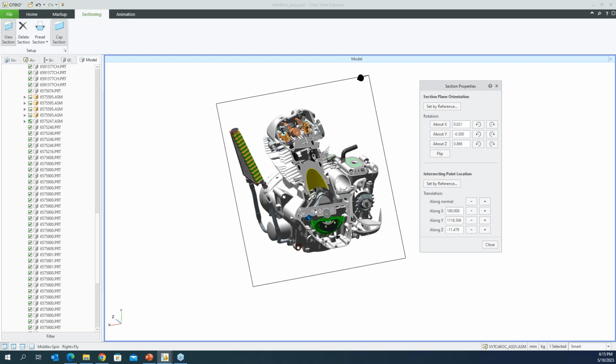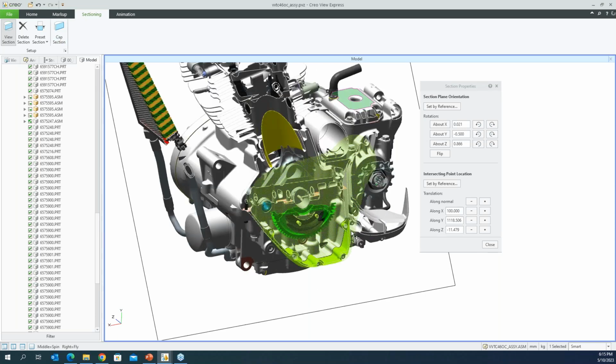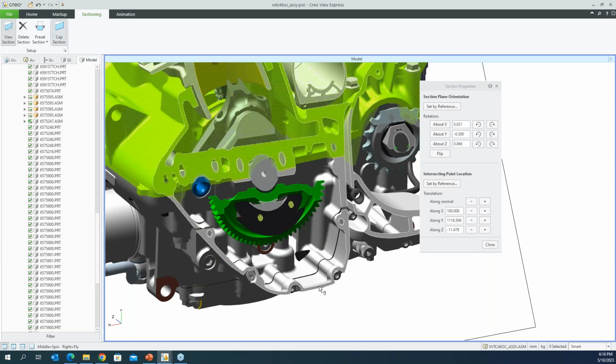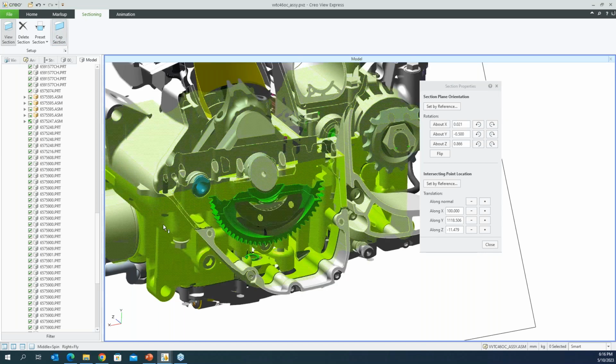And if you also don't want to see the surfaces or the cut geometry kept, you have an option there. So it looks a bit hollow. If you zoom into it, you'll be able to see that now it looks hollow with the kept option deselected. With the kept option selected, it looks as if it's closed at the end there.